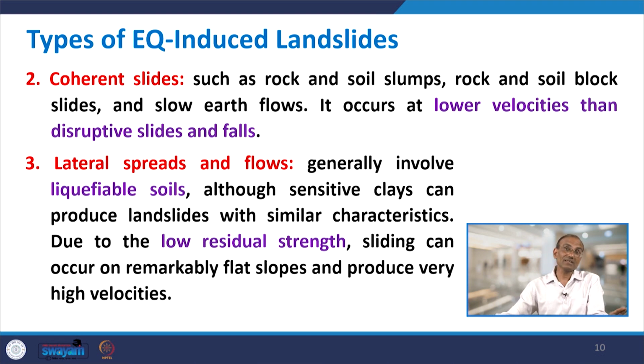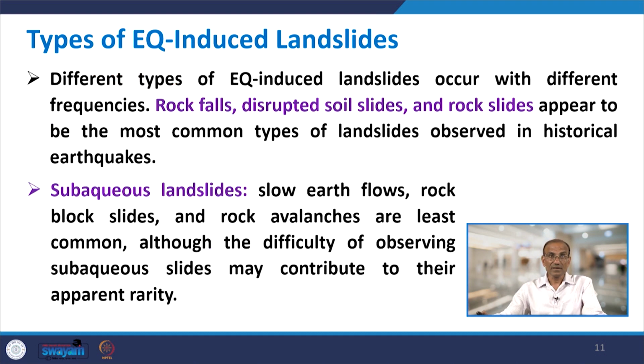So, in this case, the slide may occur on a very gentle slope also, and the reason is mostly lateral spreading. If liquefaction occurs, it is what we call inertia or weakening instability, which we are going to discuss in detail later. So, this is a different case than the normal, because in liquefaction the soil loses its shear strength. That is why it occurs.